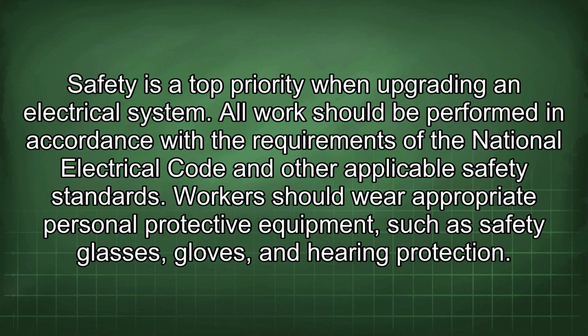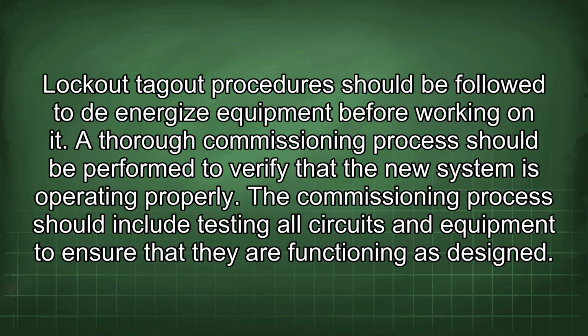Safety is a top priority when upgrading an electrical system. All work should be performed in accordance with the requirements of the National Electrical Code and other applicable safety standards. Workers should wear appropriate personal protective equipment such as safety glasses, gloves, and hearing protection. Lockout-tagout procedures should be followed to de-energize equipment before working on it.